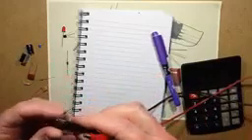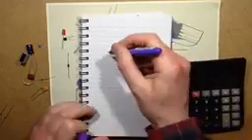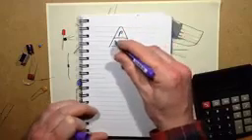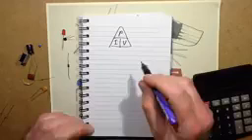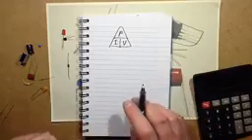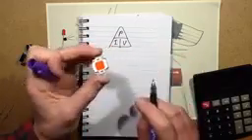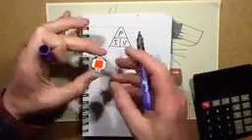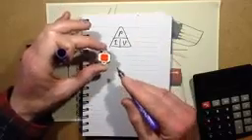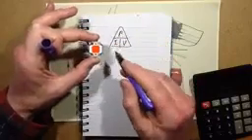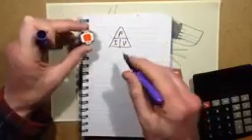So yeah, you have to choose the correct power rating for resistors. How do you work that out? That's where another formula comes in. Very simple. Triangle again. P, power, equals current times voltage. So say for instance, let's choose an example of this interesting 10 watt red LED, which has a voltage when it's operating of about 9 volts and requires about an amp, which, to give it the power rating of the LED itself, that's the 9 volts times 1 amp is 9 watts.